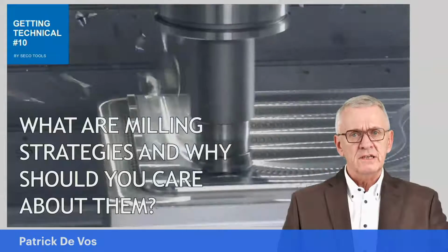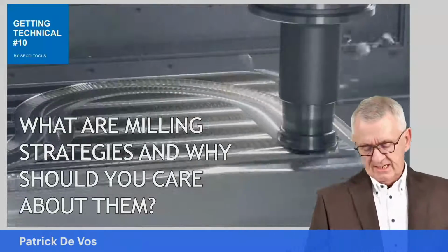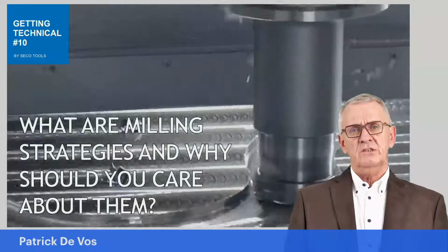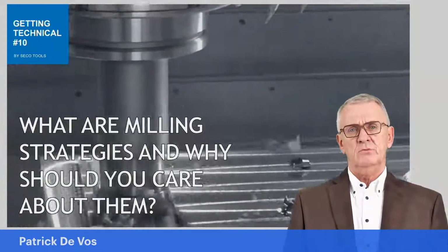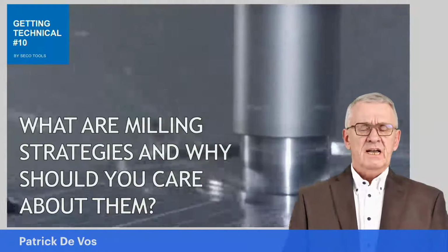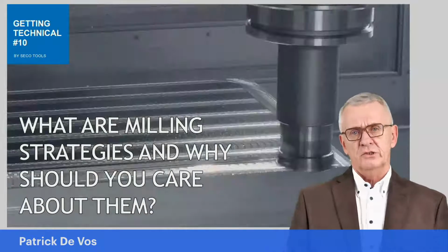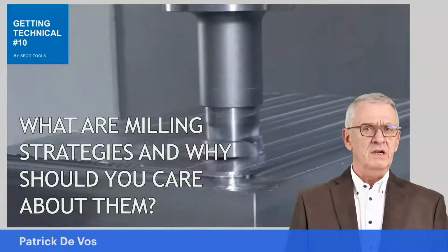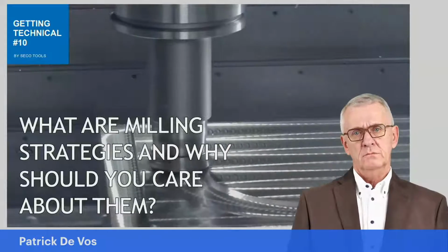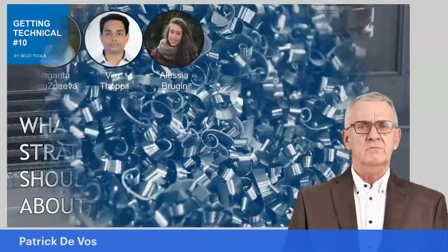Dynamic milling, is that a strategy or is it a slogan again? Because dynamics is, in mechanics, the subdomain where we learn about the interaction between forces acting on a body and the movement of the body. That's dynamics. And a specific chapter in dynamics is vibrations, harmonic movements. So dynamic milling is milling with vibrations. I don't think that's a strategy, that's a problem. So be careful when we talk about things, is what I would like to ask you.